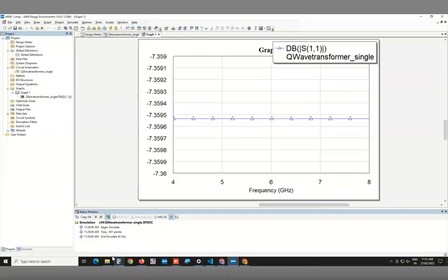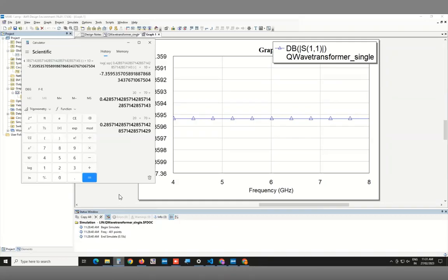Okay. So you have to remember that magnitude without dB is the voltage reflection coefficient, but magnitude with dB is the power reflection coefficient in dB. I don't know why they have chosen this, but it's because in dBs, we almost always only look at the power reflection coefficient. That's why it is like this. Okay. And the convention there, the definition, is 10 log ratio of powers, because gamma is basically giving you the ratio of voltages. If you square that, you get basically the ratio of power.